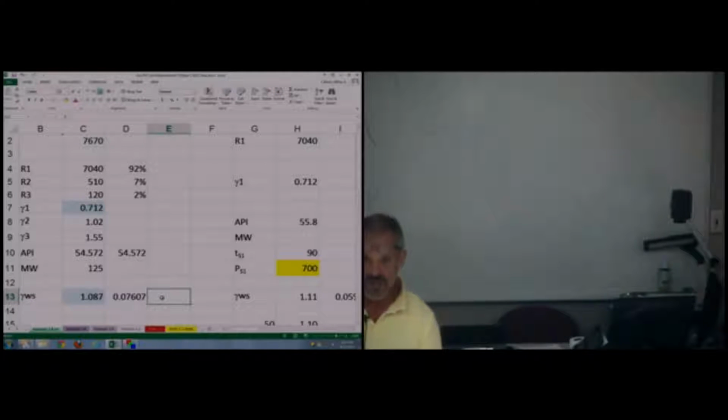Diagnostic fracture injection test. Okay, so what they do is they've drilled their vertical and horizontal well, and they've only perforated the toe. And then they pump some water, brine, mud, something in there until they can break the formation. And they're accurately measuring the pressure. And liquid gradients are really much easier to calculate than gas gradients.